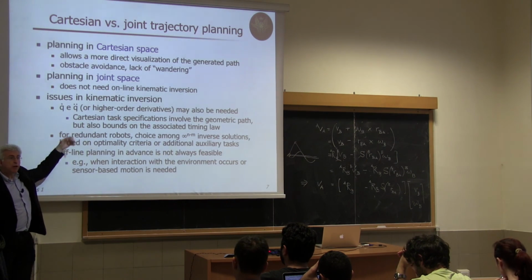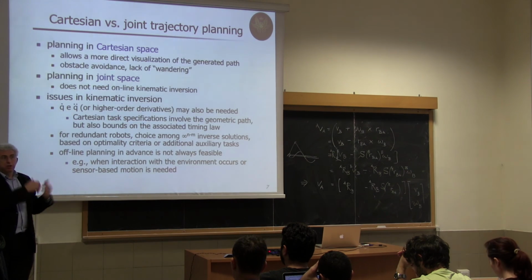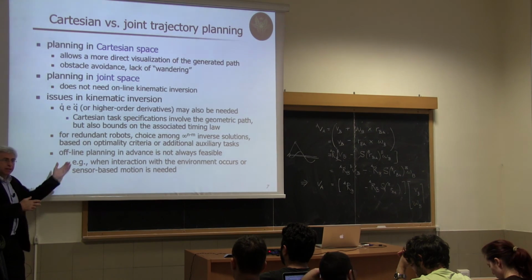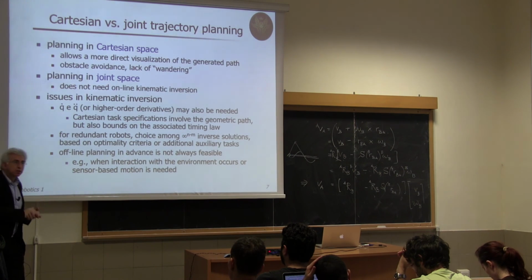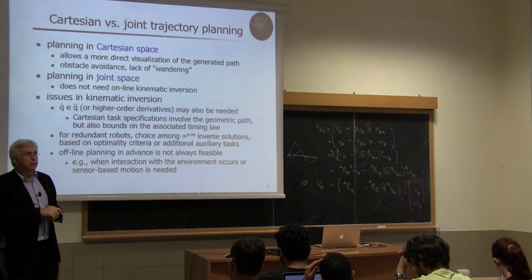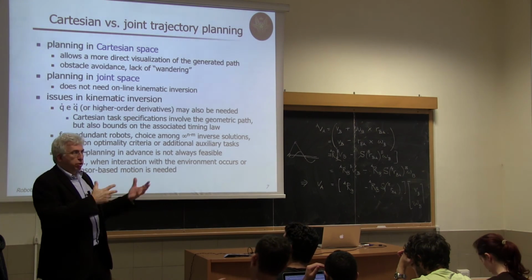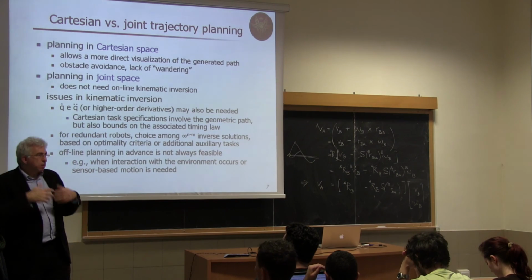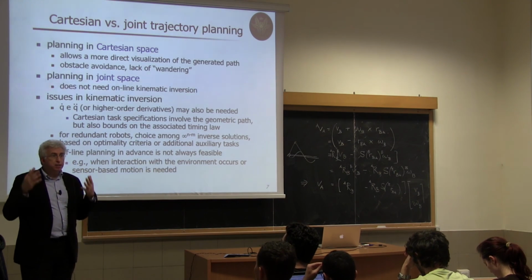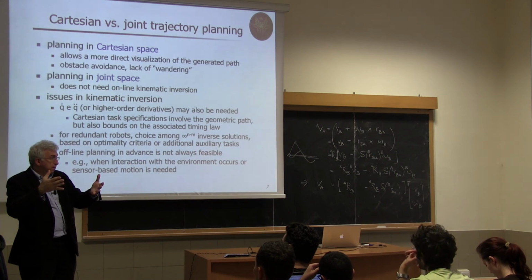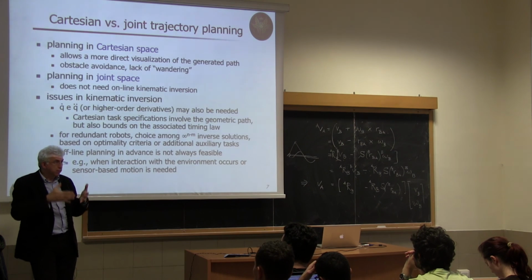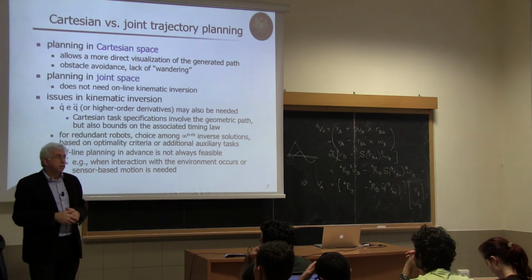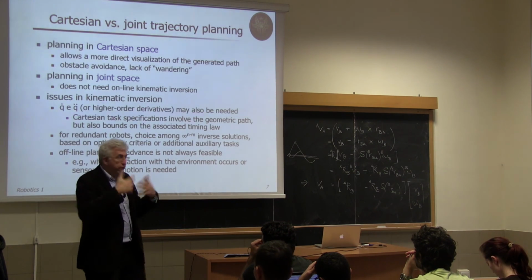Then there are other things. I've mentioned before, I need to invert just the pose in the example that we have made with the circle. We had A, B, C, and then the knots. This needs to be inverted. But of course, there's not only position or pose or orientation, there is also the possibility of having specified some Cartesian velocities. And then in that configuration, I need to invert also the velocity mapping so that the joint motion has the right velocity that guarantees also the velocity at the end effector level. Same for acceleration.